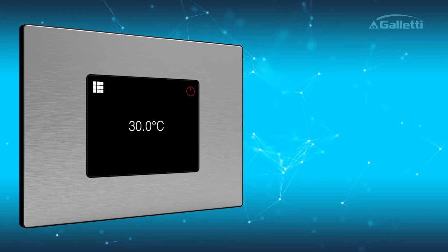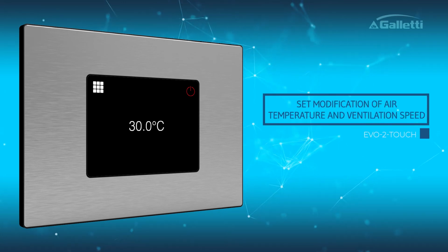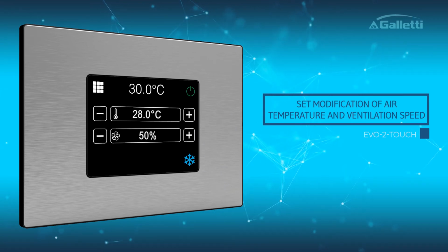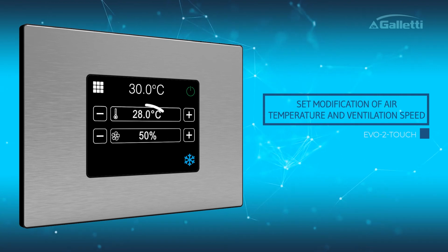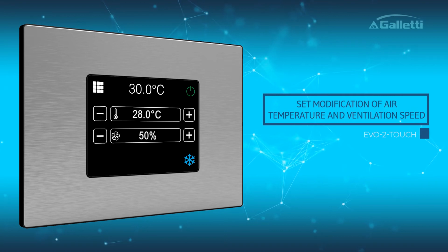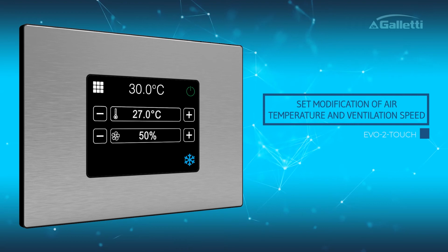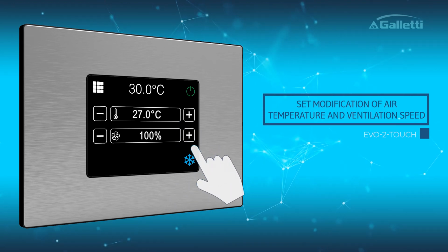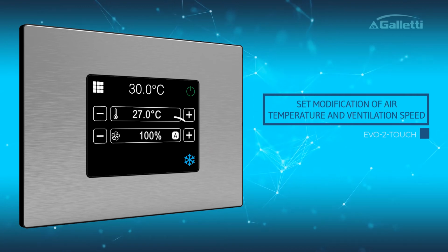To change the air temperature and fan speed set point, on the home screen, press the On button in the top right corner. The screen with the room temperature and the temperature and fan set point will be displayed. To increase or decrease the temperature and the fan speed, press the plus and minus buttons. If the fan is the modulating type, the speed will be displayed as a percentage. Above 100%, the automatic mode is selected.